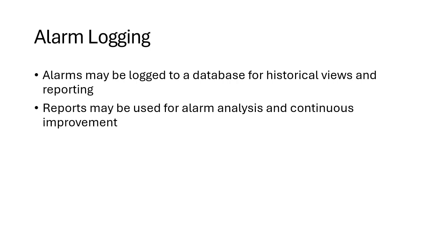So since we often have a computerized HMI SCADA or distributed control system, it's very common for alarms to be logged to a database so that we can have historical views and reporting. Those reports can be used for alarm analysis after the fact, and they can be used for continuous improvement. So very common for that alarm to be put into a database. Sometimes that's used like a black box. So a black box flight recorder, just like in an airplane, you just record all the alarms regardless whether you know you're going to need them or not, just in case.